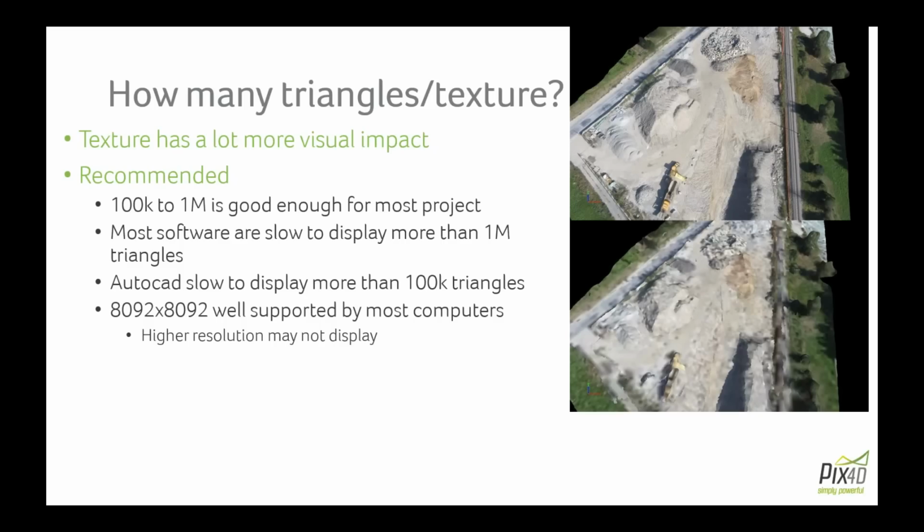So whenever you do a project where the goal is to export it to AutoCAD, I would even limit it to 100,000 triangles and not try to go over that. And 1 million, so 10 times more triangles, for most projects will not give you a significant improvement in terms of visual quality. The texture, however, is much more important.